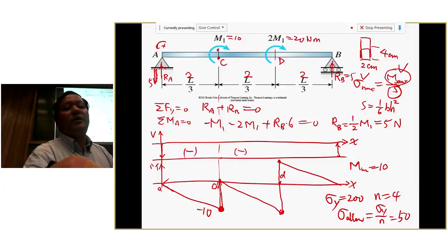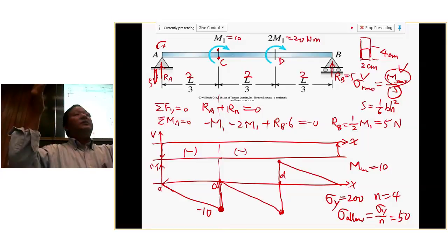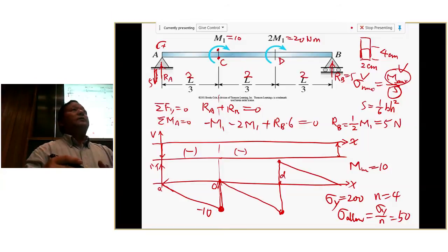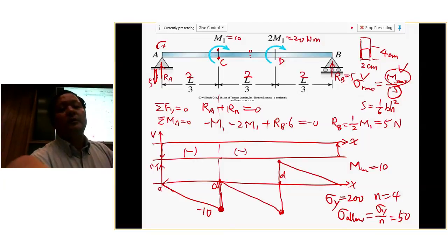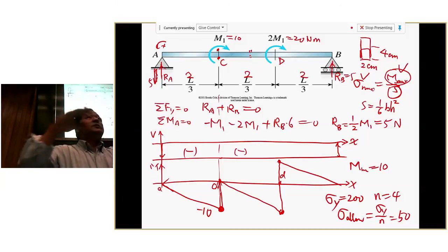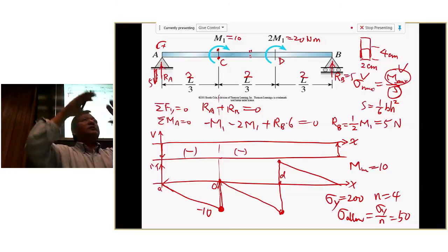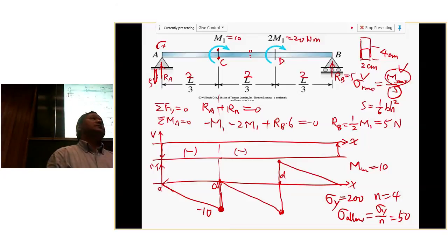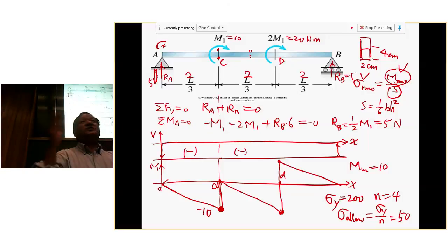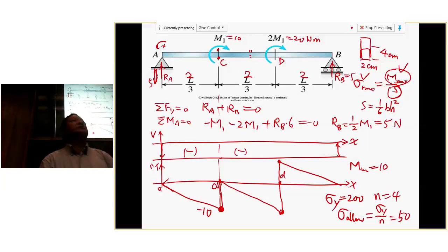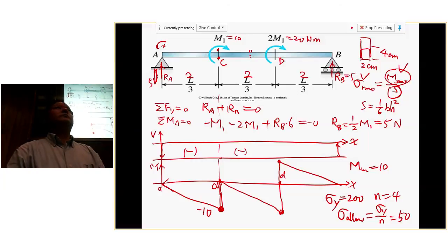And then the negative will be here at the top. If you have a negative movement, let's say this one, it will be opposite. So basically, for the top and the bottom, one will be compression, one will be tension, depending on positive and negative. That's basically the difference. So positive and negative change the location of the point where the maximum tension occurs. But for safety, it doesn't matter, right? All right, that's a good question. Any other questions or comments?